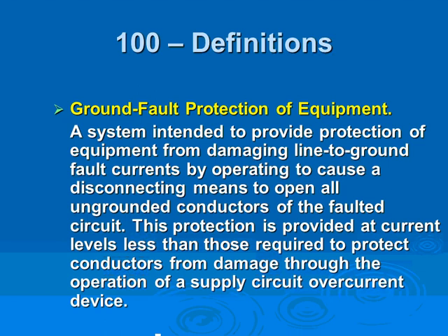a ground fault protection. This is a tiny couple of sensors. Let me go to phase A, put the sensor on it, phase B, phase C, and the neutral. And they're looking at the current coming out and the current coming in and back of the neutral. There's substantial difference between what came out of the three-phase and what came to the neutral. What do you think, where this current went? Ground, and they can trip or alarm.